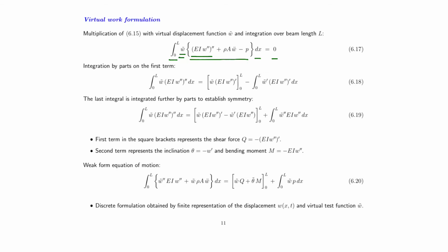So we write up the first term, and we will again use integration by parts. So if we do that once, we take one of the two external derivatives and we move that to the test function. Thereby the test function has a first order derivative, whereas only a single derivative is still differentiating the parenthesis, representing basically the bending moment.